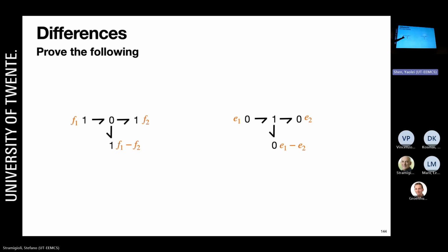Look at this. If I write the one junction now, I know that all the bonds attached to the one junction have the same flow. So I can call the one junction the flow junction, for example, and I can indicate the value of the flow at that junction, because everything has the same flow. In this one junction there are attached whatever things, and all the bonds have the same flow, so I can say that the value of the flow is the velocity.